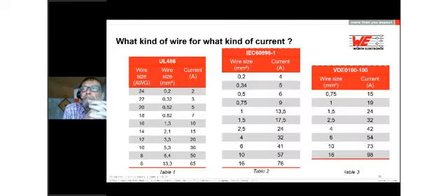There are some certification organizations which give us some rules for that. Regarding the UL, again, we have the UL 486. And the UL 486 says, for example, if we have a wire size AWG12, we can apply a maximum of 20 amps current on this cable. And the wire size in square millimeter is 3.3 in this case.